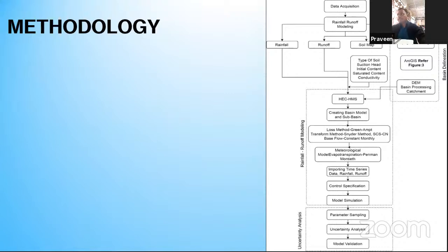You must understand, HEC-HMS doesn't consider any of the basin delineation parameters in its modeling. It's just the representation in the background. It doesn't have anything to do with its own basin delineation parameters like other models do. Suppose you consider the SWAT, it has something to do with its basin delineation. But here in HEC-HMS, it's just a background image. It means you have to visualize your modeling area completely, and only then come to your simulations and analysis part.